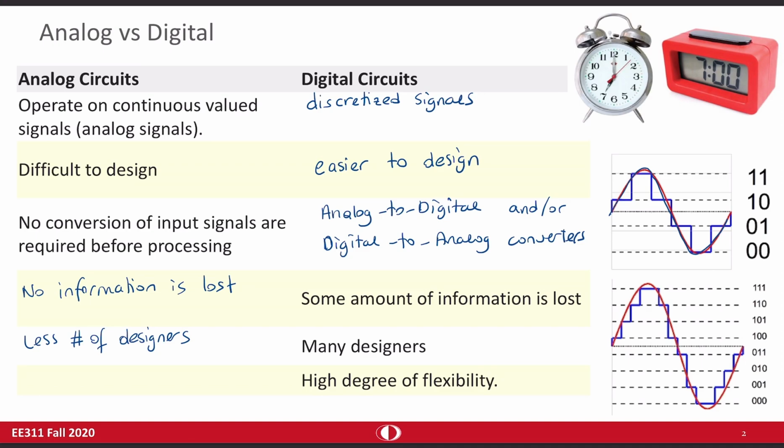And digital circuits have much more flexibility because you are dealing only with high or low voltages. It's either 0 volts or 5 volts for a design, for example. So when you are carrying that design from one end to the other end, even if you lose some voltage, that 5 volts may decrease down to, let's say, 4 volts, but it's still quite close to 5 volts. So on the other end, the person dealing with that can recognize it as still high. So losses inside the circuit, like resistive losses and capacitive losses, may become less significant because high and low level or binary operation saves you.